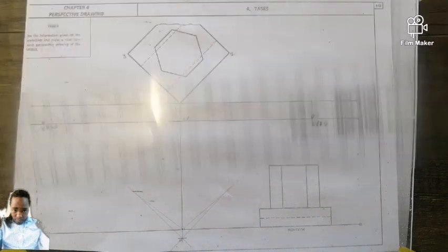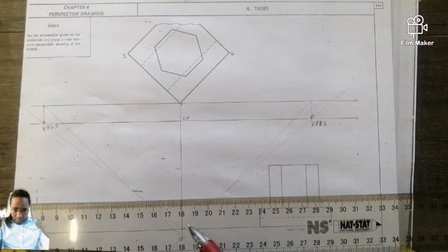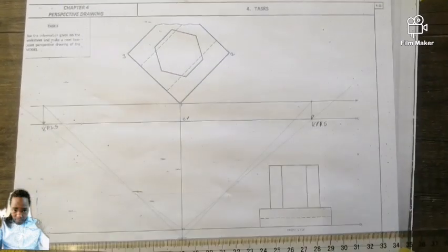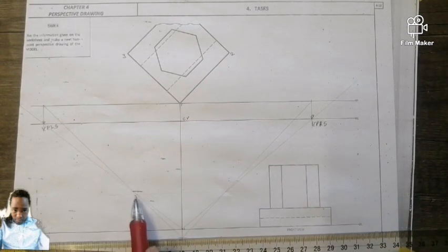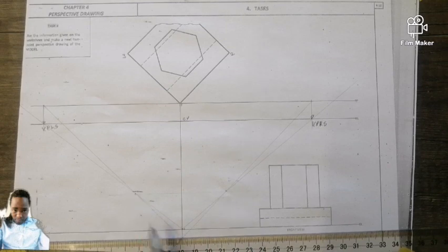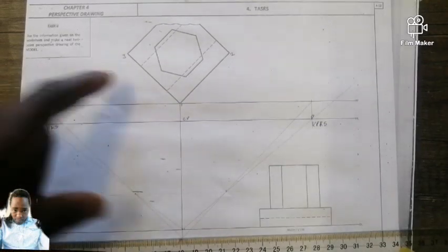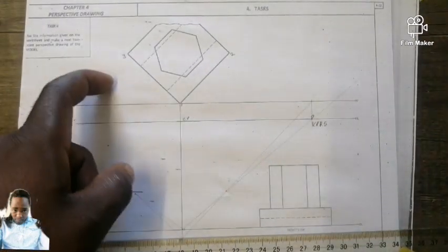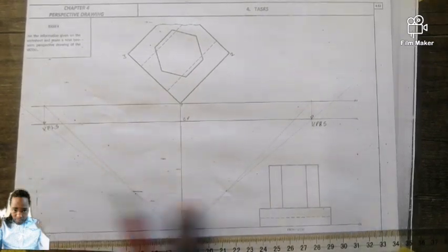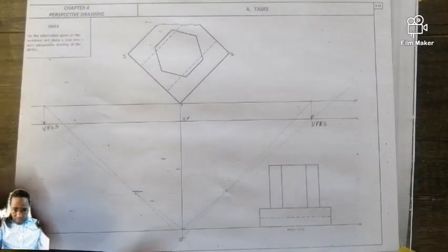And if I come to your drawing, I put this T-square. Where these lines are cutting each other, they must be in the very same straight line. Do you see? Why? Because of these both angles, they were the same. It's 45 and 45. But if it's 30 and 60, it won't collide in this horizontal straight line like that.